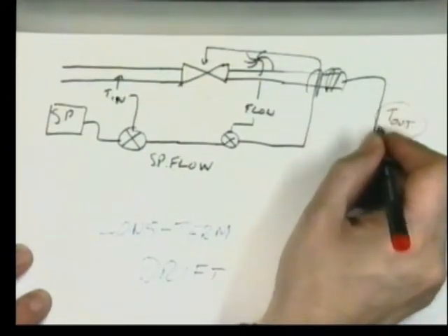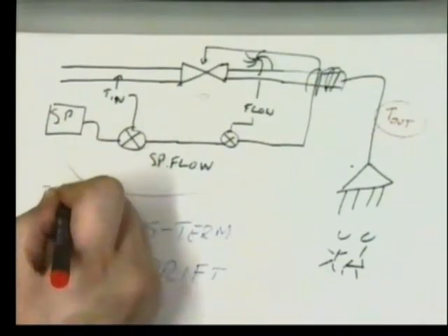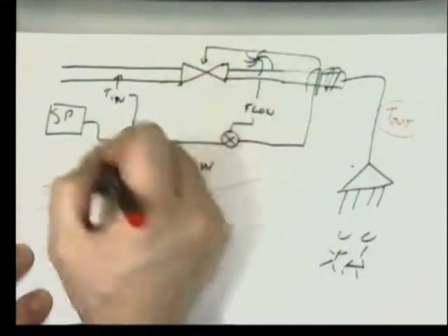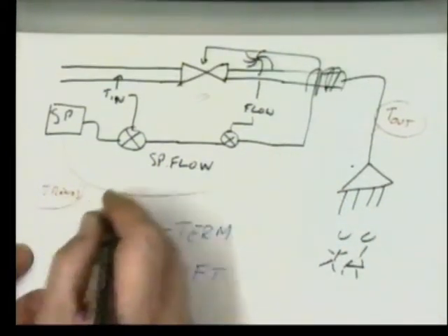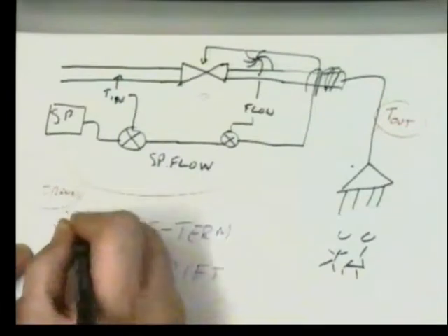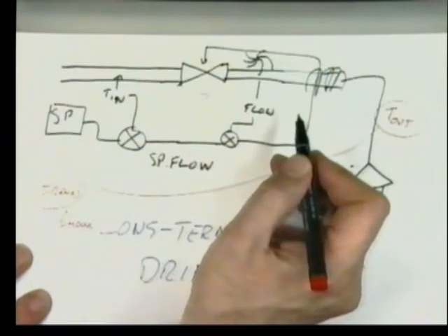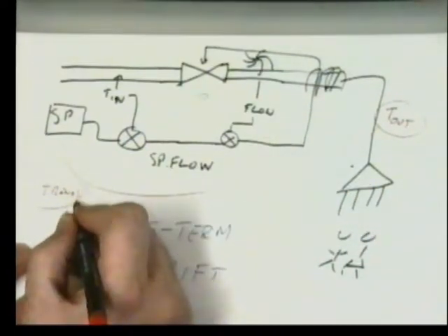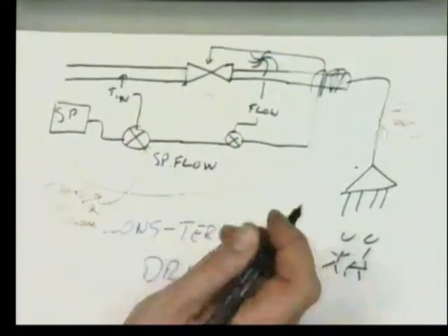And over a very long period of time, we compare that with the set point and we look at the trends. So we let this operate in a feed-forward control manner in the normal way, but over a long period of time, and in fact it's done over an 8-hour period, we monitor how effective this control algorithm was. And if we monitor a trend to be too hot or too cold, we change the model. We actually adapt the model. It's a self-tuning algorithm. It's a very complex problem.